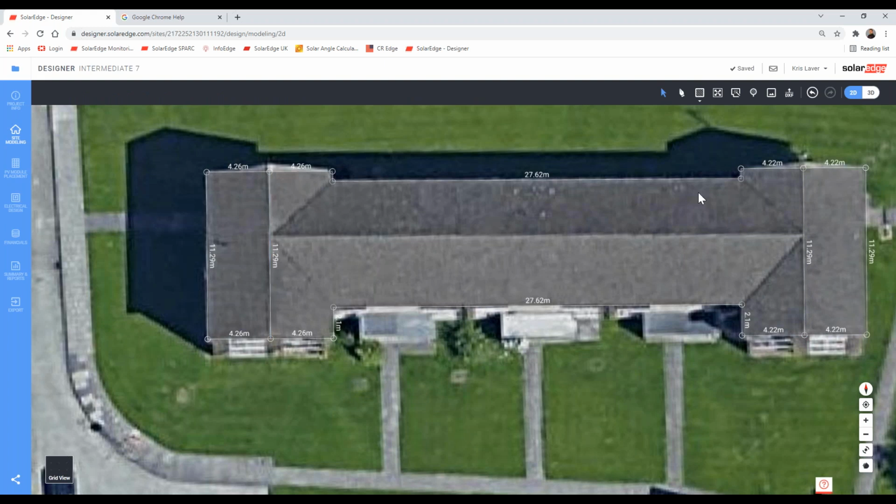However, that's not the true ridge, because this length is obviously longer than this length here. So what you want to do is anywhere along this line, connect the two up. Now find the center of the line and ensure it's dark green, i.e. it's parallel with these lines, and connect it up. You can now remove these. They were just guidelines.